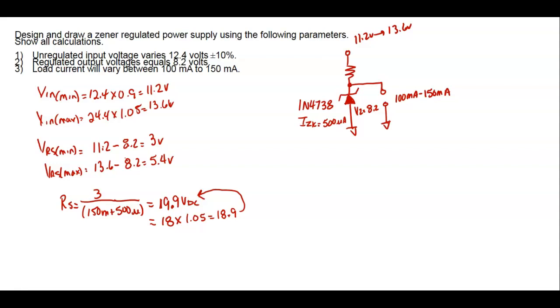So if I use an 18 ohm resistor and it's 5% above that, then this circuit might work and the next circuit might not. One might regulate and the next might not because it's within 5%, right? You understand? This guy was on the high end, sitting up here at 18.9, and wouldn't work because I didn't compensate for it.